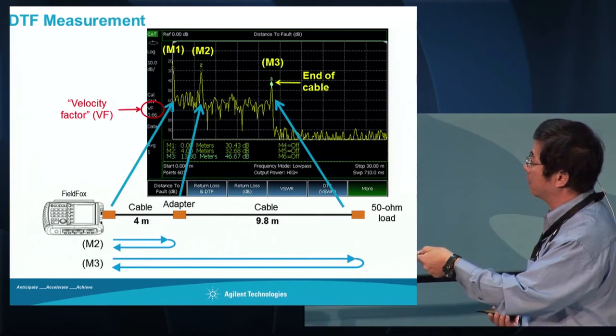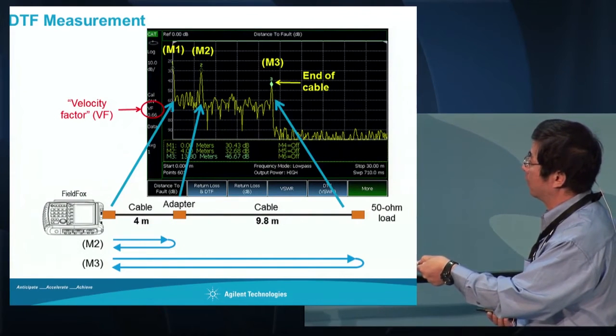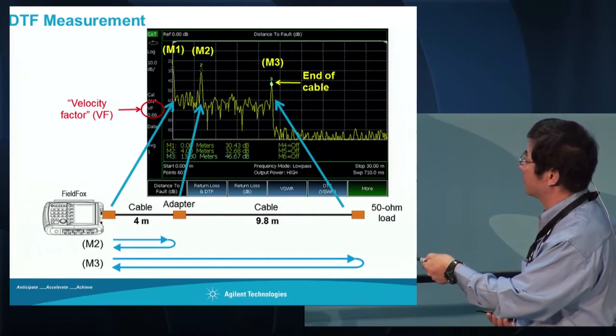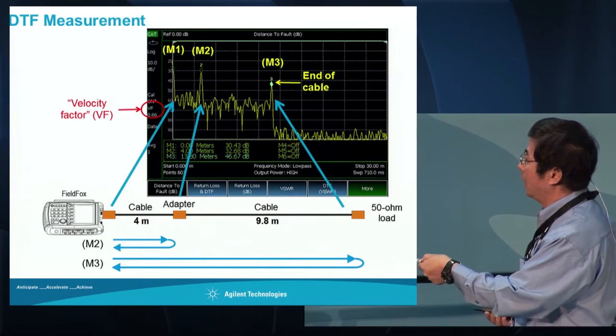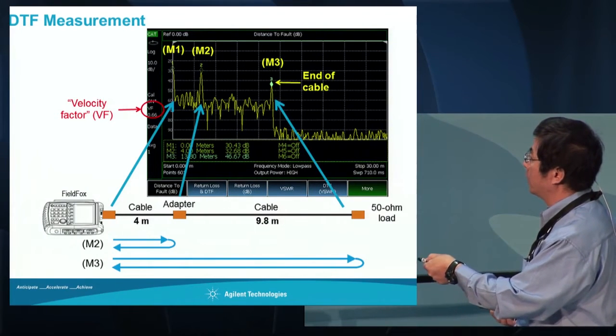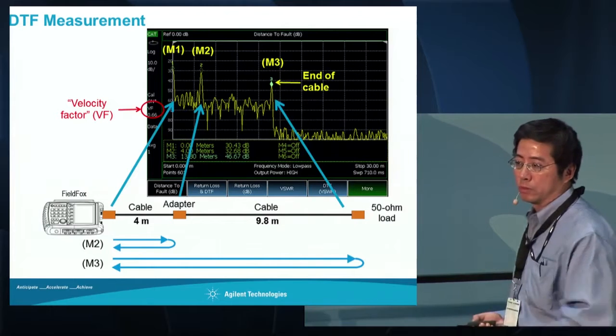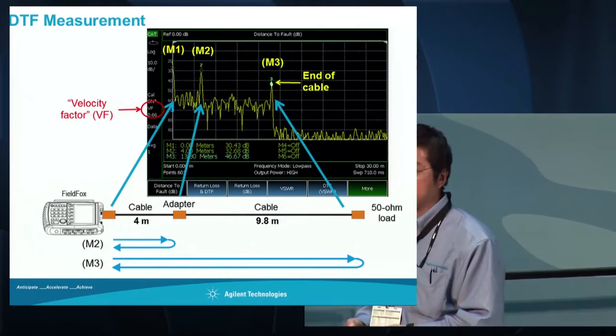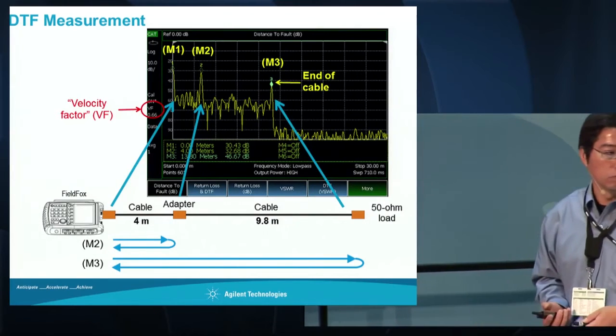For example, we simulate here a cable with 3 adapters and cables. And you can actually read each adapter and each connection and what the return loss is. This is a really neat feature we call system sweep. So when you go to any kind of feeder system, including antenna or cable, you can do a quick sweep, and it can roughly tell you what's wrong with the system.